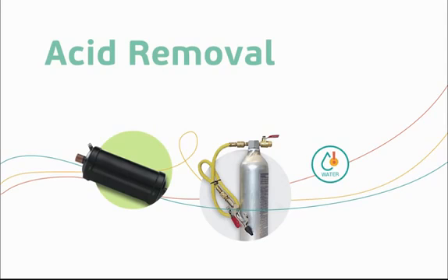Pressure drops should not exceed 2 to 3 psi, and it is recommended to remove the suction line filter once cleanup is complete. Excessive pressure drop in the suction line will cause compression ratios to rise and capacity to drop, leading to an increased load on the compressor and possible overheating.